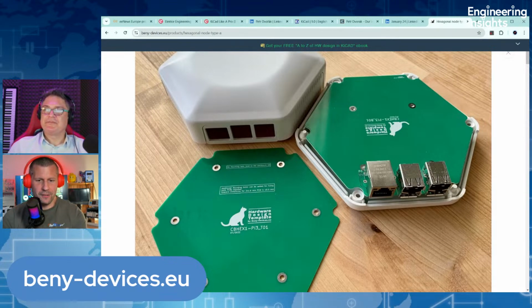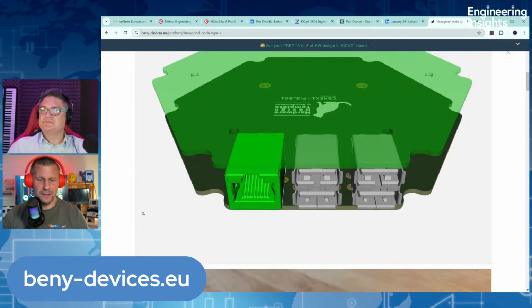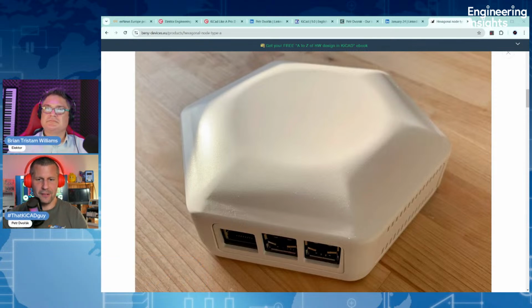I verified the exact types that fit into the enclosure openings, and the positions on the PCB are verified. So you can grab it, route some tracks, and place other components. I don't say that the prototype will be first time right, but at least the mechanical design will be flawless.